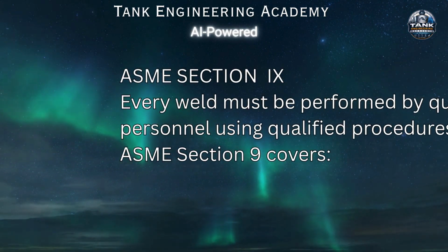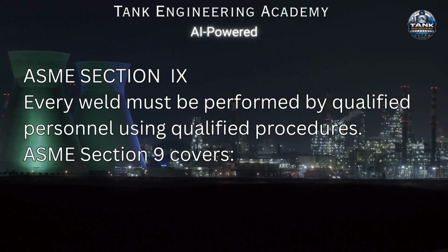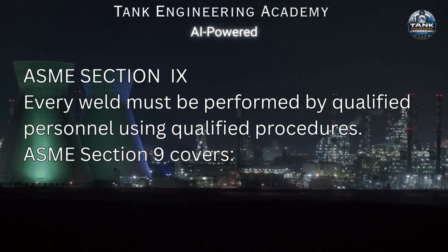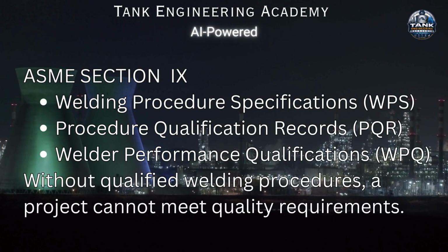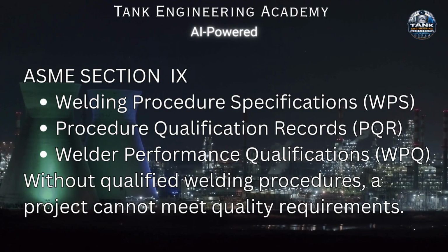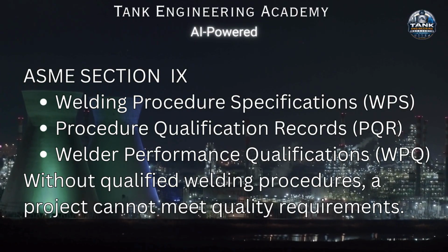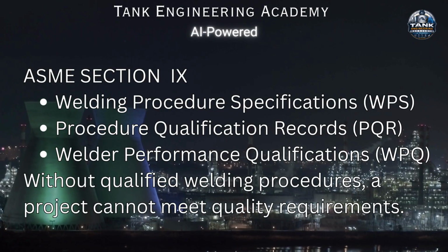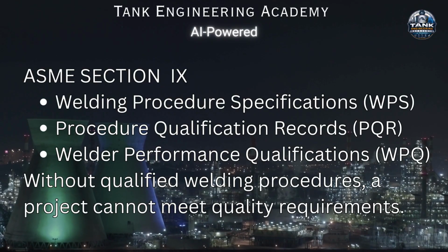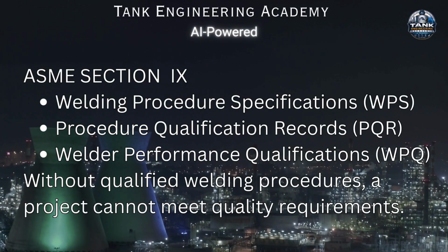ASME Section 9. Every weld must be performed by qualified personnel using qualified procedures. ASME Section 9 covers Welding Procedure Specifications, WPS, Procedure Qualification Records, PQR, Welder Performance Qualifications, WPQ. Without qualified welding procedures, a project cannot meet quality requirements.